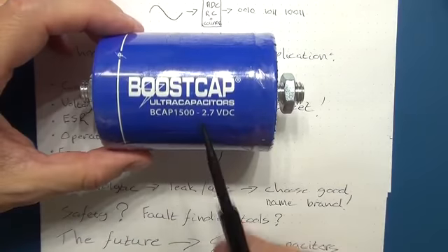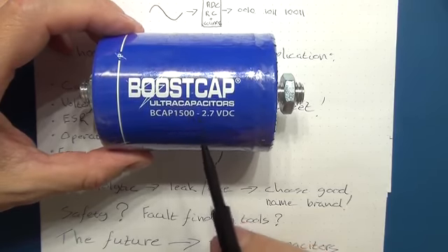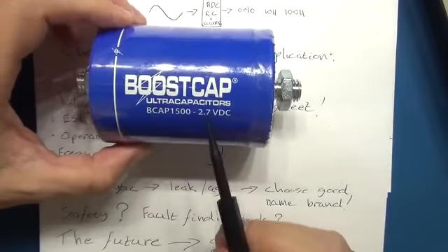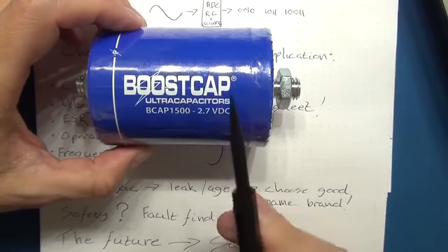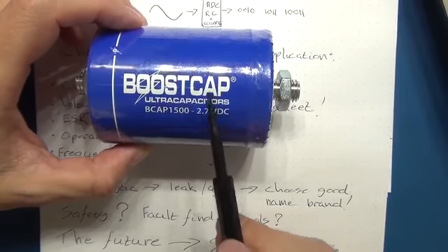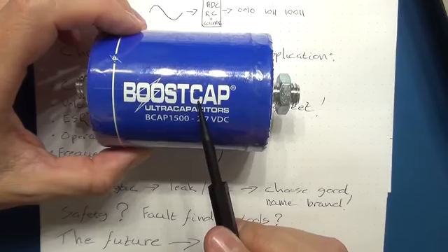This capacitor will release hundreds of amps, if not into the 1000 amps. In fact, this capacitor and this one over here, if you short discharge them, can release over 1000 amps, and that can do a lot of damage. It will melt things, it'll spark, it'll crackle. The capacitor could explode because of the quick release of energy.